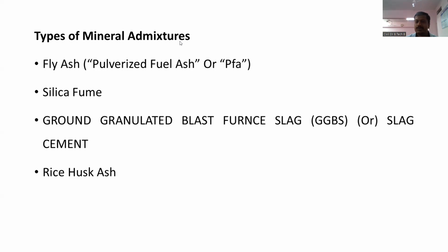कन्स्ट्रक्शन डस्ट, ज्यावेळेस तुम्ही रोड मध्ये बघितलं असेल, ठीक आहे, किंवा बांधकामात सुद्धा तुमच्या बघितलं असेल, डस्ट ॲड करतात ती लोक. Actually first thing I will tell you, you have to check whether it is recommended to you to use the dust. ठीक आहे, असं कुठेही रिकमेंड केलेलं नसतं की तुम्हाला डस्ट वापरायची आहे. ठीक आहे, जर रिकमेंड केलं असेल then you can use that dust. ठीक आहे, but the percentage of dust should not be more than 12 to 15%. How much?